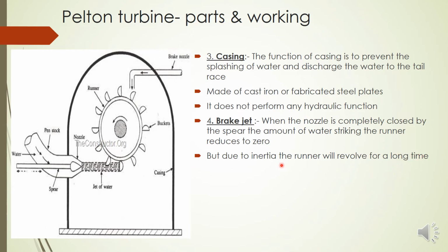So what do you mean by inertia? Suppose you are switching off a fan. Will it come to rest instantaneously? No. It will rotate for some 1 or 2 minutes, then only it will stop. That is due to inertia. So this turbine will be rotating at very high speed. If we push the spear forward and completely stop the water, the turbine will still run for a very long time due to this inertia.